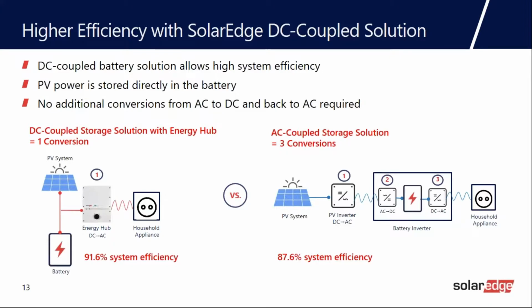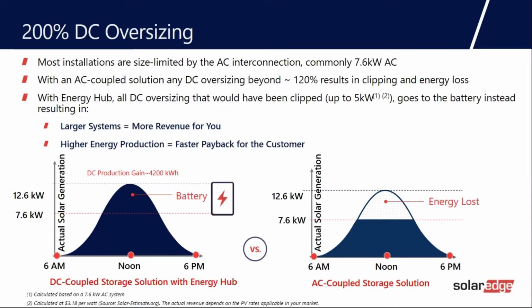So even with a great SolarEdge inverter with an AC coupled battery, and we can call this any AC coupled battery, whether it be a Powerwall or Sonnen or whatever, you're going to see that the system efficiency just suffers. So what does that mean to the homeowner and to the end user? Less energy. You lose a lot more energy when you have these efficiency losses. So if you want to maintain more energy during backup, then the best way to do it is increase your efficiency.